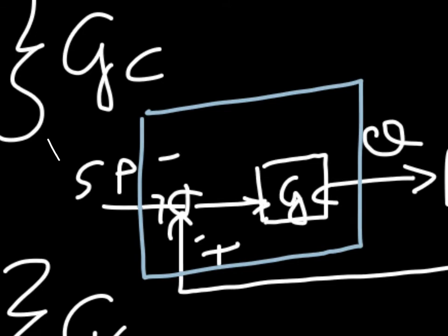Now, to keep things general, we'll just introduce a little bit of extra nomenclature. We'll be talking about YSP as the set point. And we'll also be introducing the idea that this output from the process is just also called y, and the difference between that set point coming in and the measurement coming in the feedback loop is going to be called the error. And so all of our calculations are going to be written in terms of the controller responding to the error. This is not the only way in which this calculation can take place, but it is by far the simplest. So in order to compare two values, when they are near one another, their difference is low, and when they are far away from one another, their difference is high. So the subtraction calculation is the simplest way of comparing two inputs to one another. It also has the distinct advantage that it's linear.